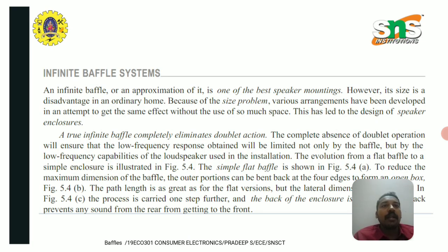An infinite baffle or an approximation of it is one of the best speaker mountings. However, its size is a disadvantage in an ordinary home. Because of the size problem, various arrangements have been developed in an attempt to get the same effect without the use of so much space. This has led to the design of speaker enclosures. A true infinite baffle completely eliminates doublet action. The complete absence of doublet operation will ensure that the low frequency response obtained will be limited not only by the baffle but by the low frequency capabilities of the loudspeaker used in the installation.